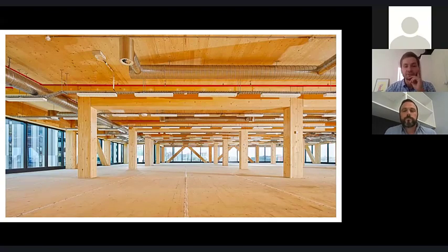Yeah, so with the post and beam type approach, I guess a limitation that I see is obviously you're going to have quite deep beams, which for a hotel building, typically you have a floor-to-floor height of, in the order of 3 meters, 3.2 sort of thing. So having such a deep structural element, that would need to be coordinated architecturally to align with the wall. It might be every third party wall, for example, or every second or something, so that can be built into the wall line ultimately. And then services, obviously, you can see here on the left that they've got a shorter grid span to allow the services to run underneath a shallower beam.